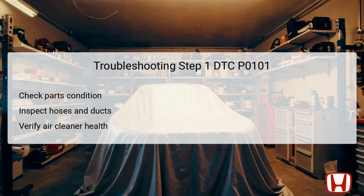The first step in troubleshooting the DTC P0101 code is to conduct a thorough parts condition check. Begin by inspecting for any poor connections or damage to key components, including the PCV hose, intake air duct, air cleaner, and purge line. A visual inspection will help identify any apparent physical damage, such as cracks or loose fittings.